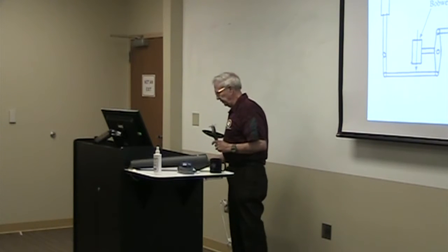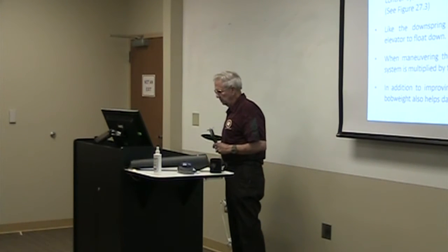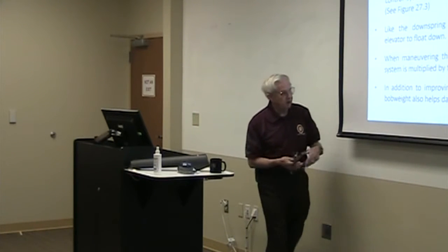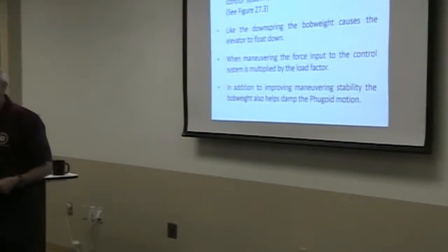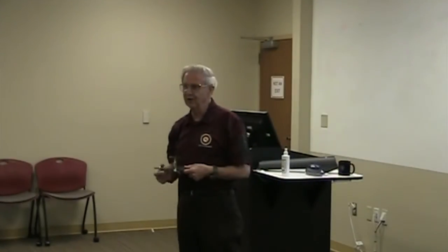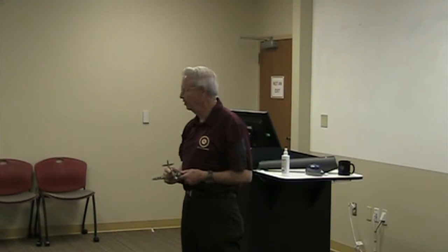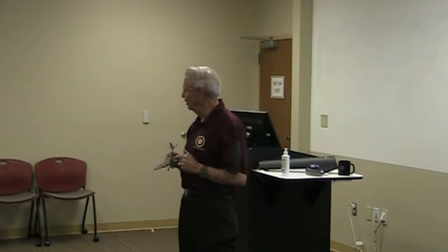Well, what's wrong with it? And, oh, by the way, I forgot to mention, it helps damp the phugoid because the weight has inertia and it's going the other direction when you're doing the phugoid oscillation. Okay, so it helps move the elevator and damp that phugoid motion out. Great. What's wrong with it?